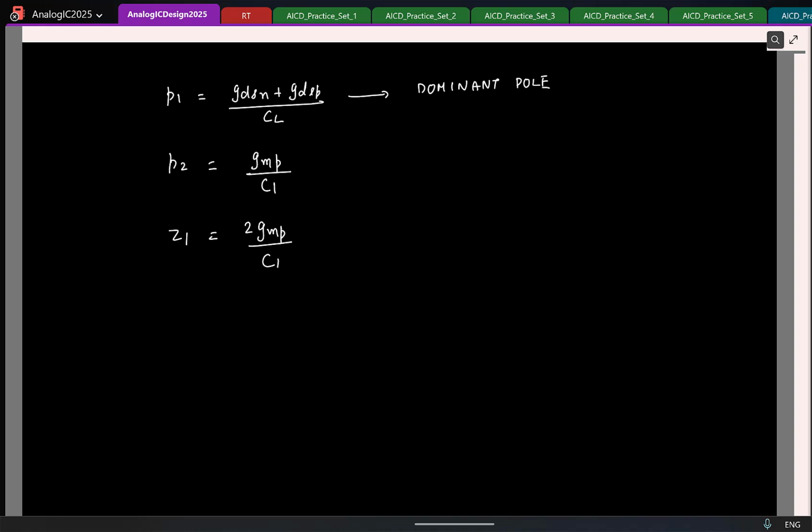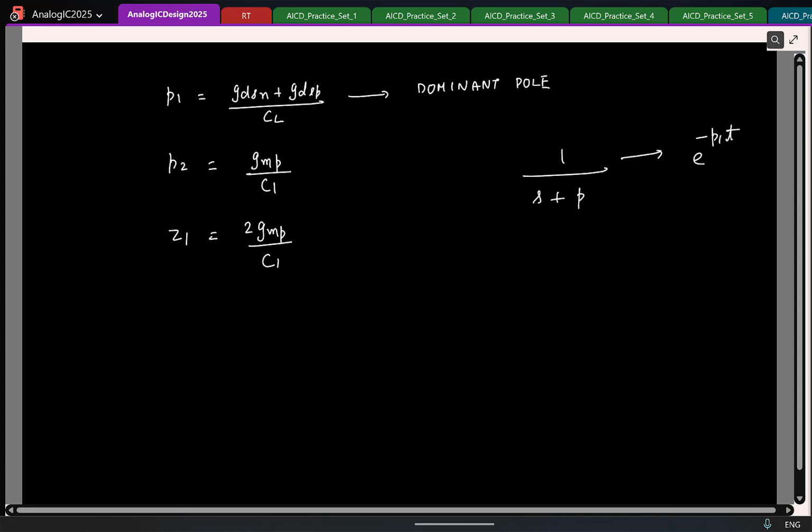Yeah, so why is, I mean, okay. The transient response is controlled by that. Can you elaborate? Correct, it's right. So what do you mean by it's controlled by this? The system speed is controlled by this pole. Yeah, see, if I had to put this into other words, if I have a transfer function having a pole like this, what is the impulse response of this? E power pt, correct? Let me call it as p, it's e to the pt.